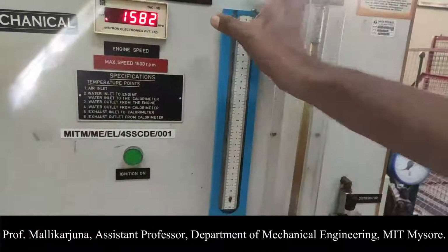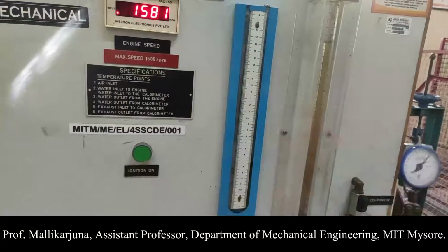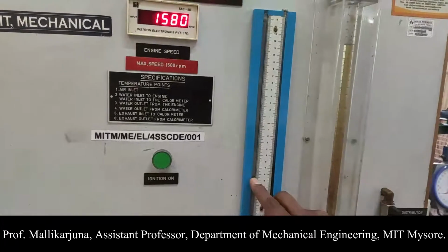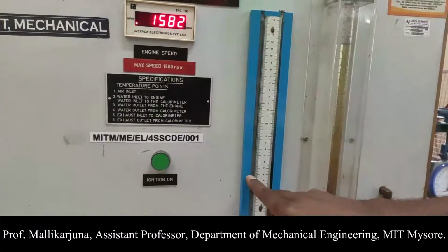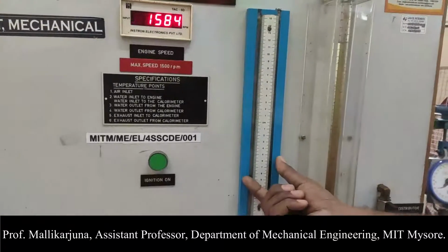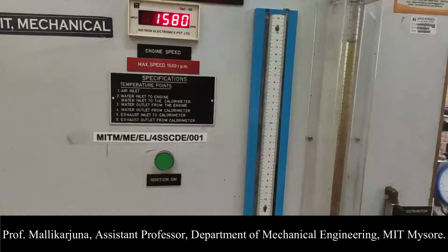Now here we have the U-tube manometer with which we can look onto the pressure with which the air is entering into the cylinder. So the knob differences, mercury meniscus distances should be noted down over here, so that we will get the pressure with which the air is entering into the cylinder.